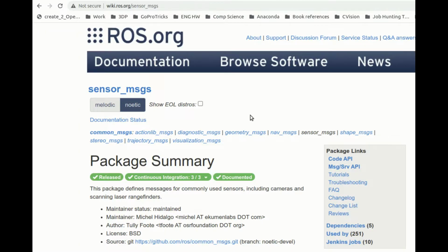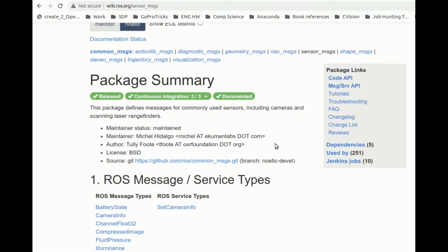So being able to look through some code to see why something is not working as expected can really go a long way. Now, I'm not suggesting you wait to start robotics until you're a master programmer. I'm just saying when you're working with something and you don't understand why it's not working as expected, take a look through the code. Go to GitHub, or sometimes download a package directly into your Catkin workspace source folder instead of using sudo apt install, and then you can actually play around with it. Make little changes, see how it helps or doesn't help. Maybe just print out some values to the screen and start to learn how that software works. And definitely get used to looking at message definitions for the different ROS data types.